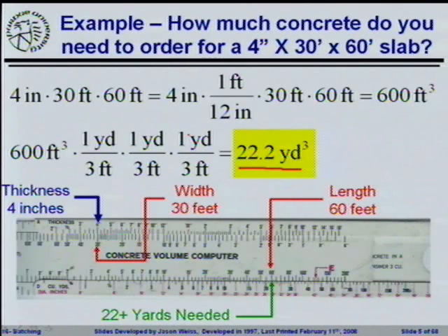You will also encounter something in the industry that is fantastically interesting, and it is a little stick that looks like this. This is a stick that's sort of a slide rule. It's a plastic type stick. I forgot to bring mine with me. I'll bring it to the next class. You can look at it. This is sort of a magical stick because it has numbers on it, and people can do very quick volumetric calculations with this slide rule concept. So the center part slides with some numbers on it, and essentially this is a very quick, easy way for them to estimate the volume. The thickness of the floor slab that they're doing is 4 inches. They set the width, they look at the length, and on the bottom it will tell you the overall cubic yards of concrete that you need to do this.